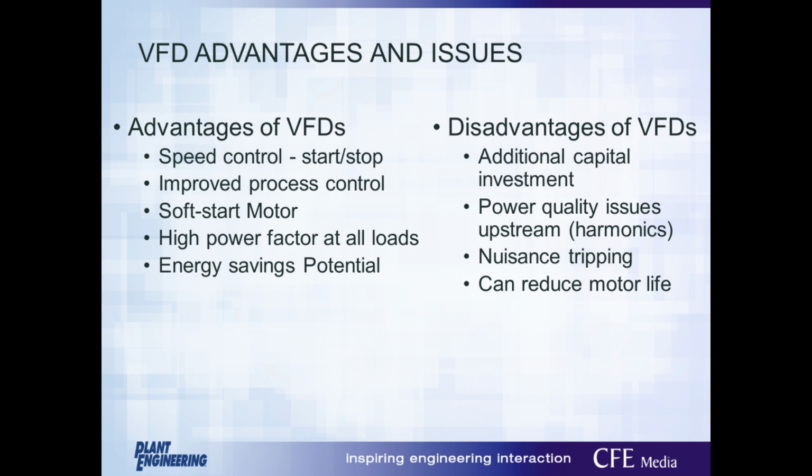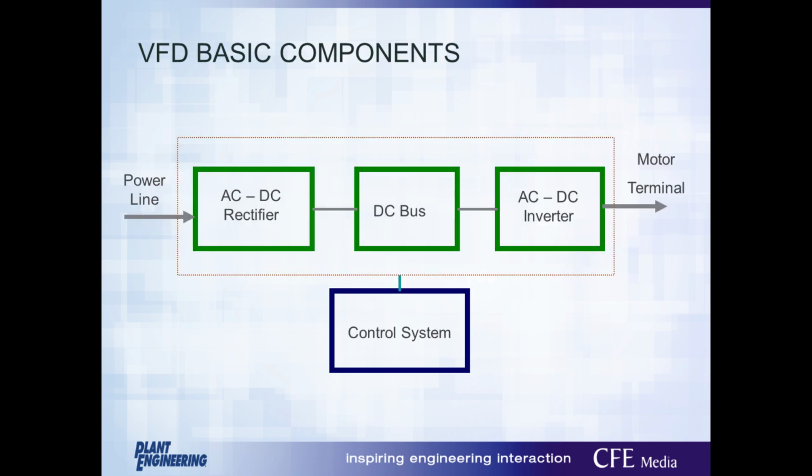Some disadvantages of using VFDs are additional capital investment. You may have to ask the boss for more money. My experience doesn't always go well. VFDs also add harmonic distortion to your system due to their capacitive nature. One other thing, you may experience nuisance tripping in your application if the VFD isn't programmed or sized correctly. And lastly, the VFD could actually reduce motor life.